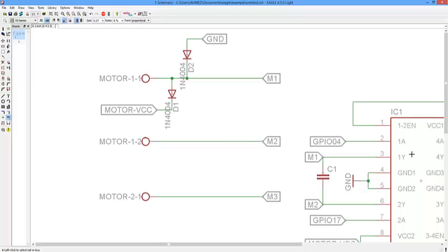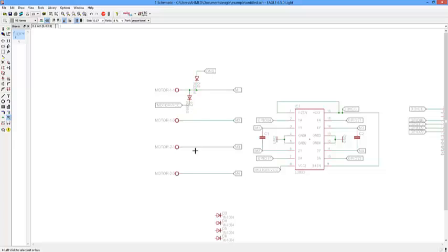And yeah, the H bridge usually works with you guys during the testing part. Everything is nice, and then you even go to the PCB and it works nicely, and then you come to the presentation day and poof, it doesn't work. Why? Because the motor just gave it a little more spike than usual and burned it. Just your luck. Anyway, so yeah, duplicate this process for the 3 wires.